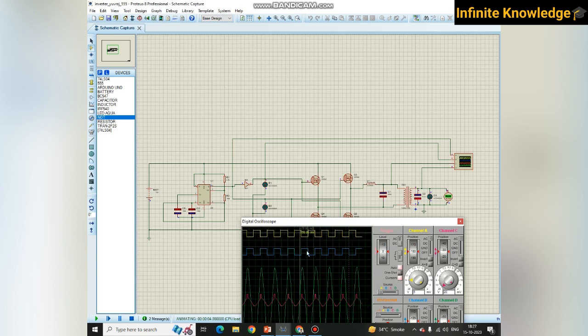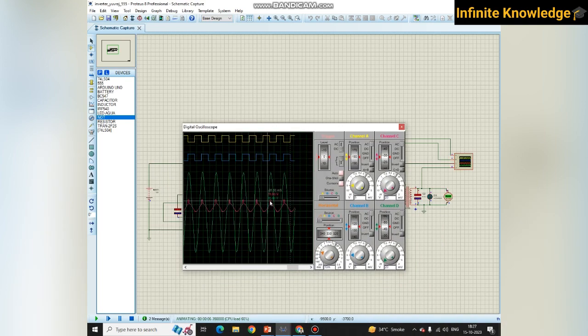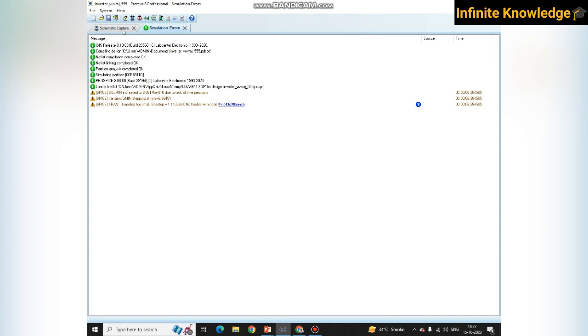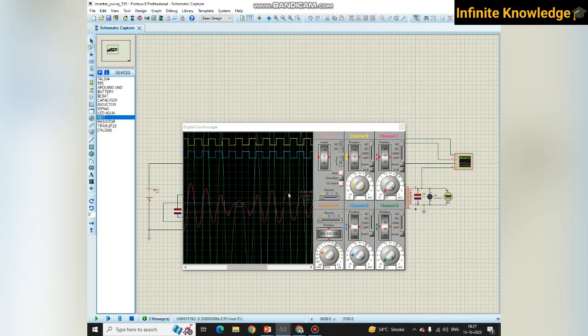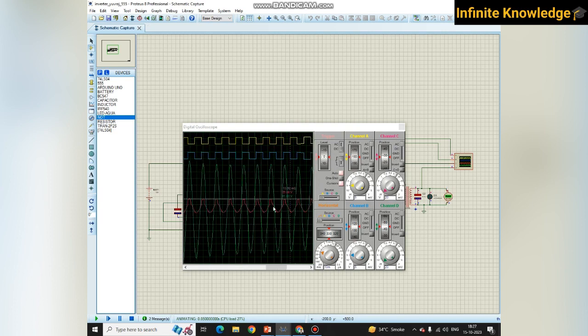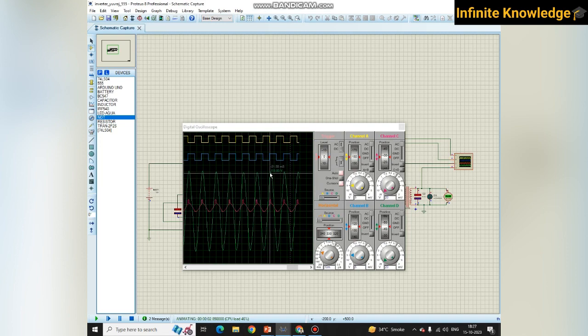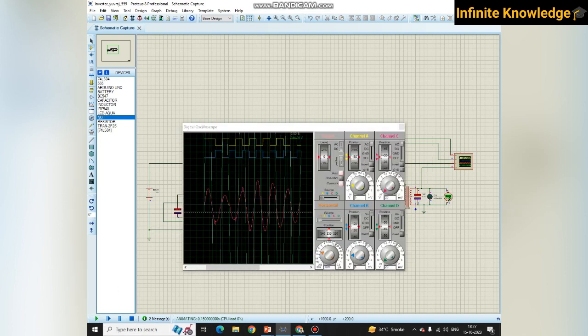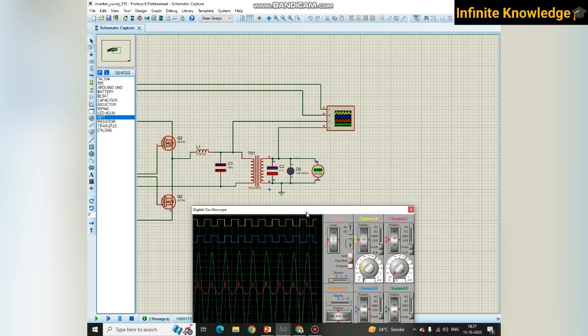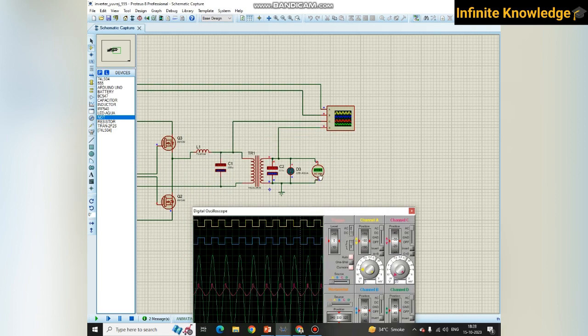So this is a similar waveform. This is the waveform you want for switching on and off this. And you can see here, this happens sometimes because it cannot handle too much load. And okay, we are trying an input of 17 to 18 volt and the output is 110 volt. Here also you can verify the voltages. It increases after some time and gets up to 110 volt.